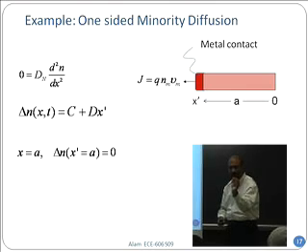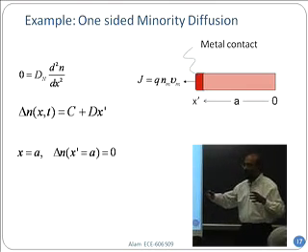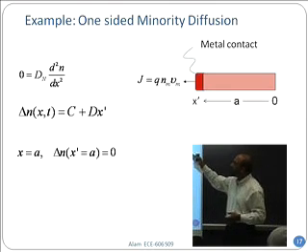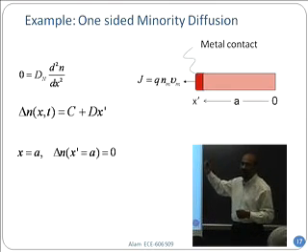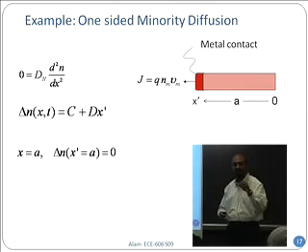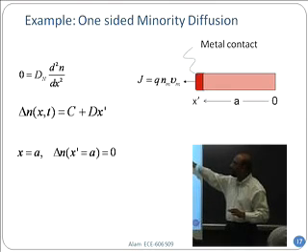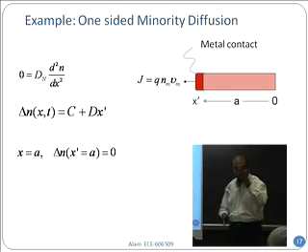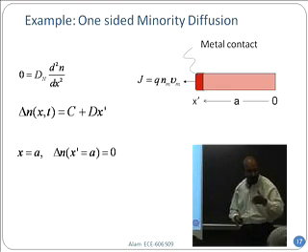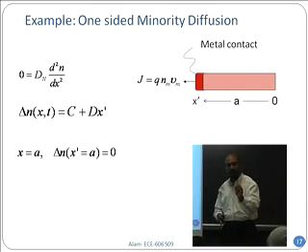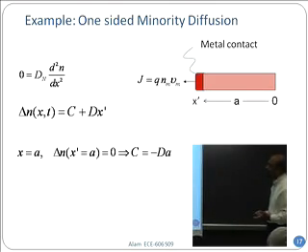It will need a very small amount of delta n, right? Because the velocity is very big. As a result, delta n is approximately equal to 0. So anytime a semiconductor is contacted by a metal, at that point of contact, I will assume the boundary condition to be equal to 0. It's an approximation, but a very good one. Do you realize this? Okay.